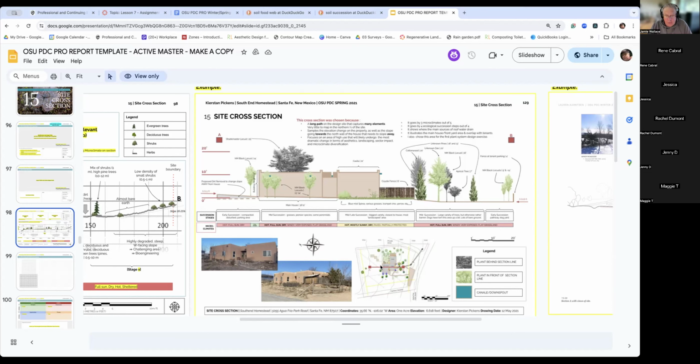So as you go along, let's say this is 40 feet and you're going down a foot, you come along this line 40 feet and do a little mark, and you're going to be coming down a foot at that point. So it's just translating the finished grade from a drawing up to the side view, or the site cross section.